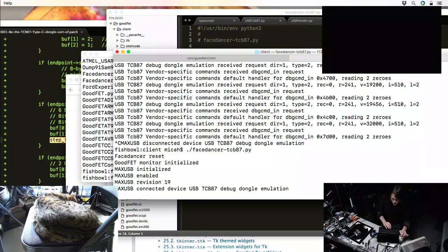I think the problem that I'm trying to dodge with that particular workaround is that if the program is running and then I unplug the device, the driver can't actually unload. It depends on how the program actually finds the device, because if the program is smart enough to look for the device that's actually active and not a zombie device that was held open previously, then maybe it's fine. But I think what's going on is the driver can't delete its instance of this device when I unplug it because the program is still open. And then if I plug it in again without closing the program, the device still exists, but it's somewhere that the debugger can't find it.